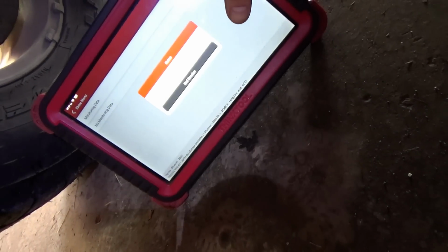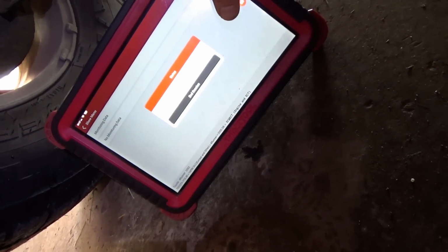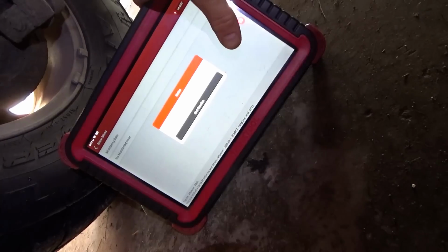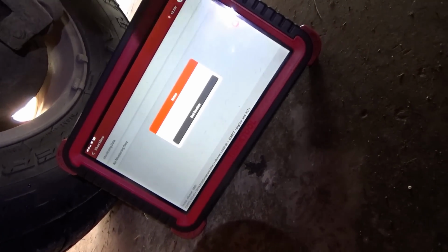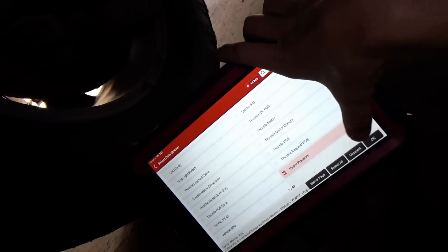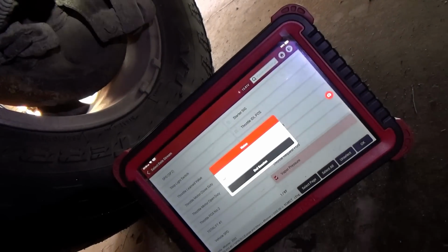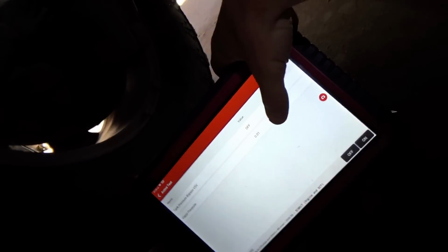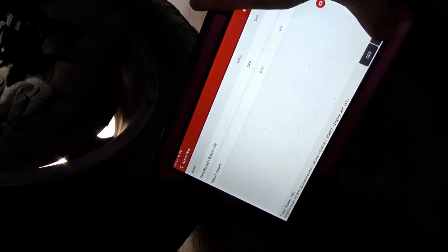Okay. And we can even look at the fuel tank pressure while we do this, just to make sure the pressure sensor is okay, and see if it clicks. Alright, let's select vapor pressure in our data list. You can see, okay, here we go, 0.01 psi, so it's at atmosphere. So let's click on.